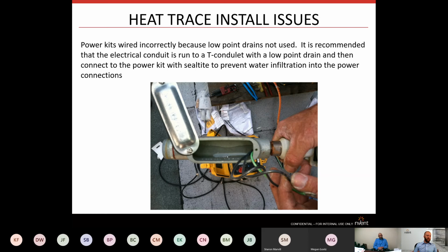The insulation is the most difficult system out of all of these components to maintain. You can imagine you have thousands of feet of insulation. There's jacketing and there's elbows. They're driving screws into the jacketing. They're caulking things. That's going to wear out. People are going to walk on the insulation.